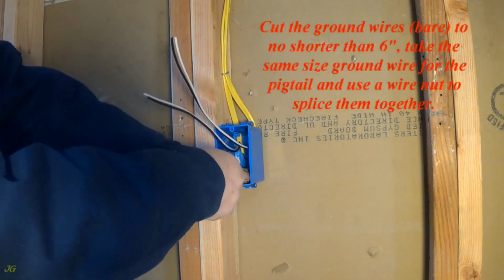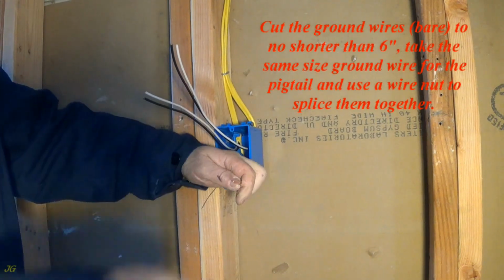Take the same size ground wire for the pigtail and use a wire nut to splice them together.